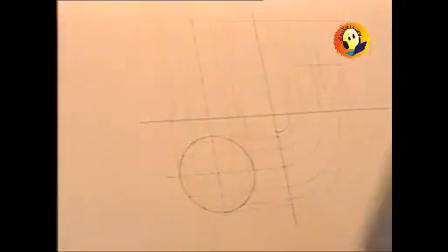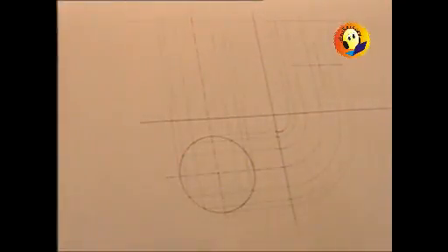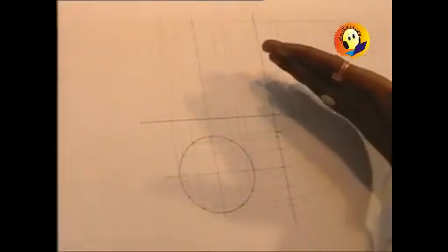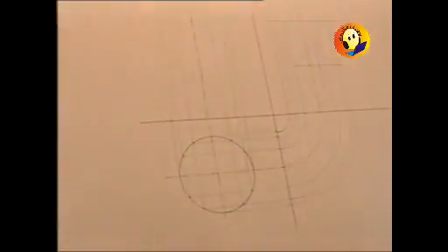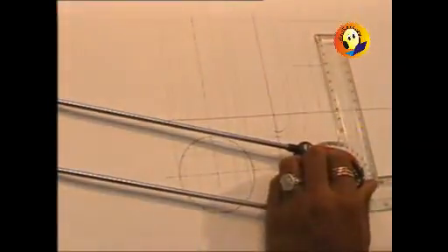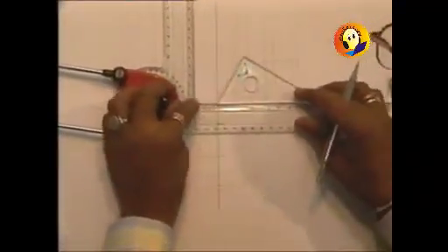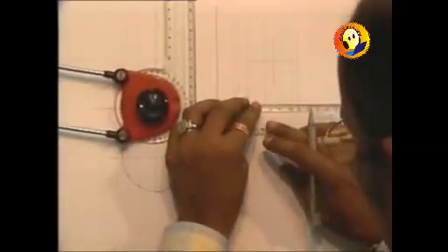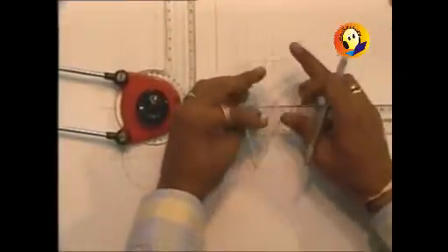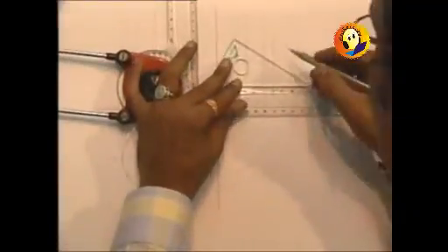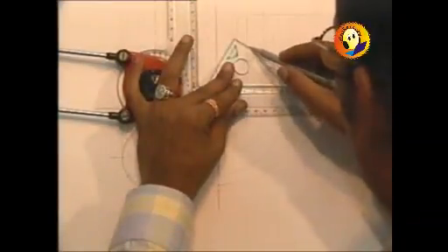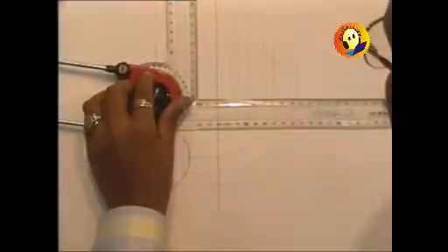But the face of that square hole is making 30 degrees with HP, so we will have to construct it accordingly. No need this time to construct it separately. We will draw one line making 30 degrees with HP, and then using that as the reference we can proceed with drawing the square.